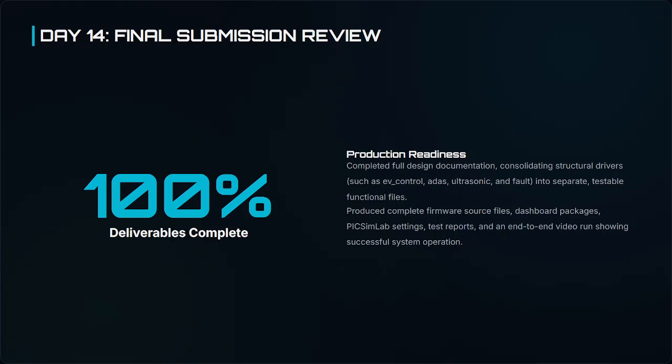EVcontrol.c manages only vehicle physics. ADAS.c runs risk assessment. Ultrasonic.c isolates low-level timer capture, and fault.c acts as our central interlock safety system. We packaged our verified STM32 firmware, the Python HMI dashboard simulator configuration files, and testing reports into our final submission. I am proud to report that 100% of our architectural deliverables are complete and passing.